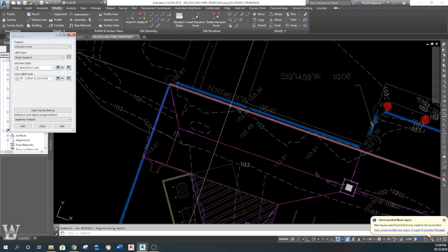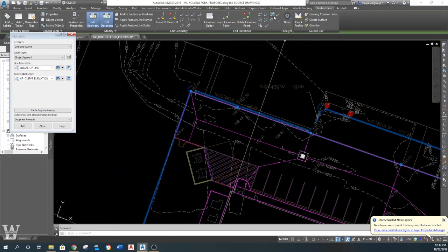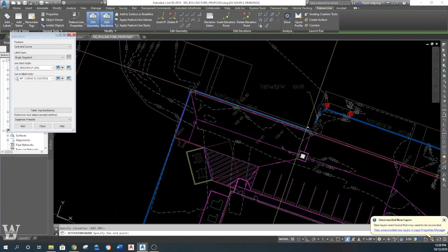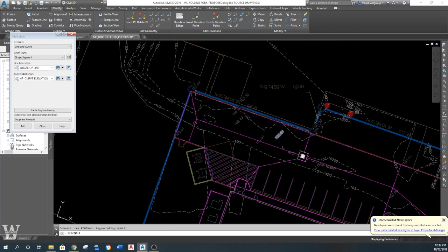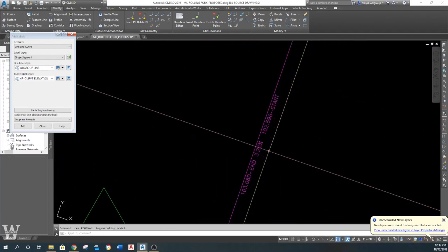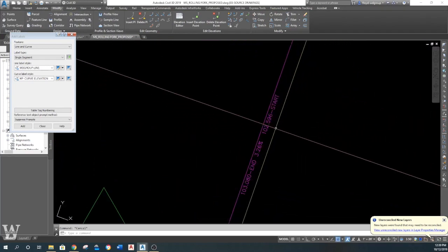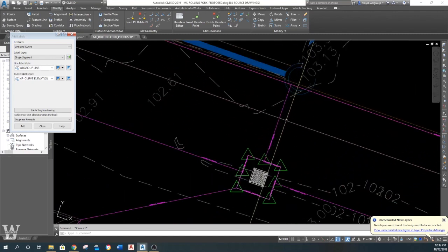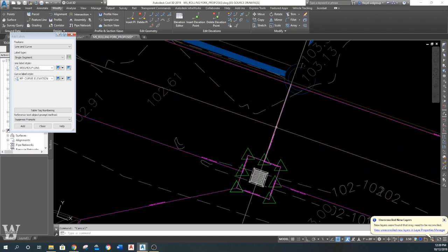103.10, 103.30. Let's just see if we do a straight line from here to here, and we grade that down at 0.75. Then what does that put that at? That puts that at 102.60. So we're too low right here, actually. That's not going to work.